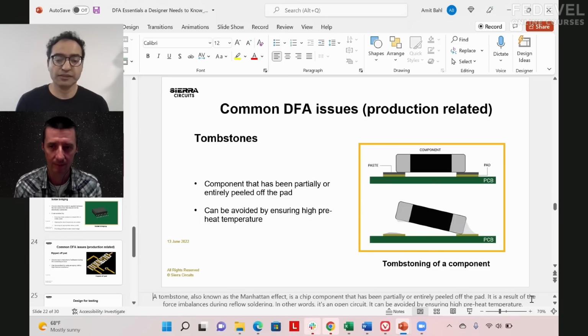If, for example, your solder mask opening is not appropriate for that component, right? And let's say that there's more copper underneath, as I say, there's a copper pour, a copper ground that goes right underneath the components. There are all these specific things that can go wrong with that component that could cause the defect. The defect is the result. You have to analyze what in your design caused that defect. It's never one thing. So that's the root cause assessment that is specific to your design.